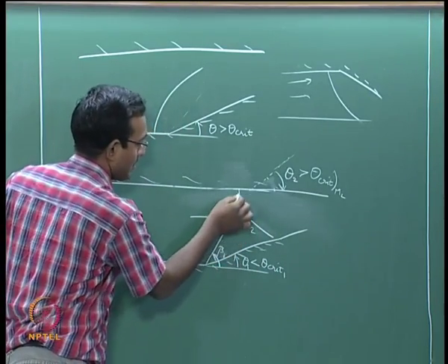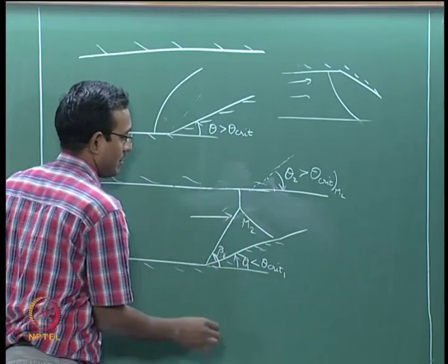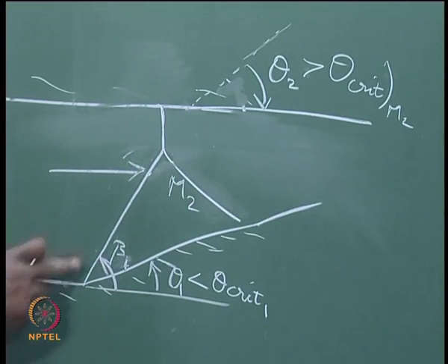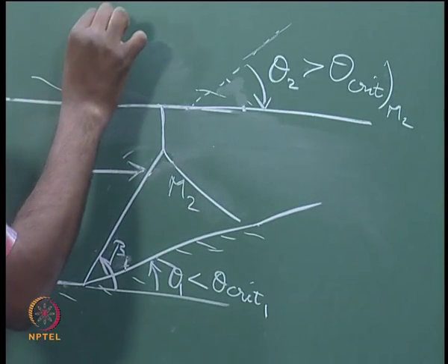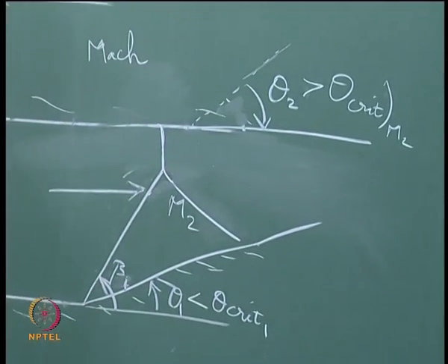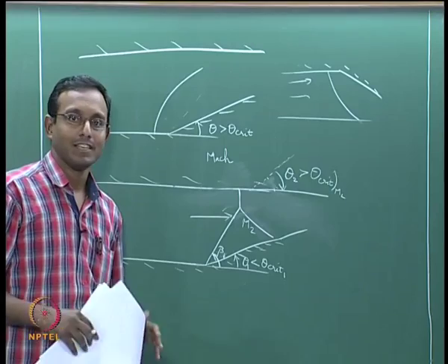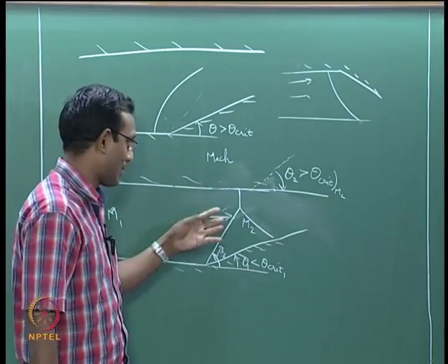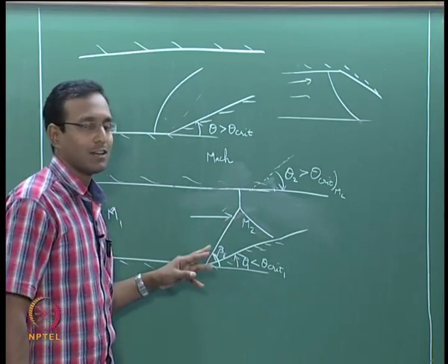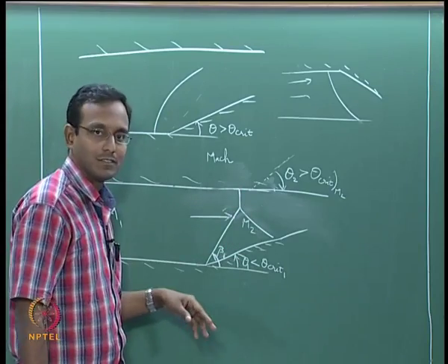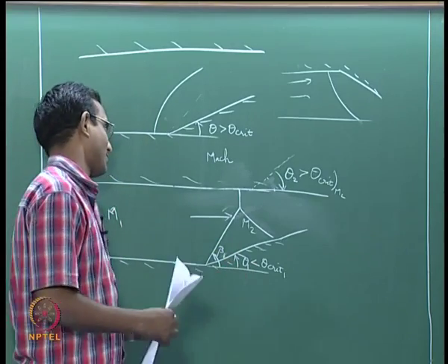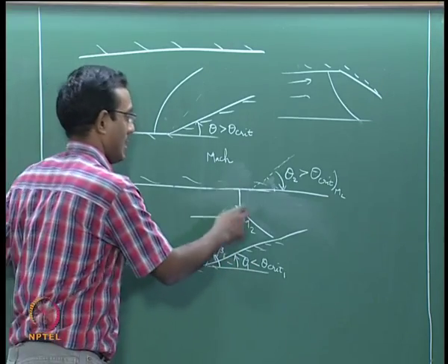What is happening here is there is roughly a normal shock sitting here, and then there is somewhat curved shock sitting here. Okay. This is what is called a Mach reflection. Again, Ernest Mach was the one who explained this very well. Okay. He explained it for blast waves traveling across wall, okay, but anyways it works very well for our case also. This is shock reflection at a wall, that is explained like this. Okay. It could be any of those reflections. All the reflections were explained first by Ernest Mach. Okay. Anyways, I am going to have this case.